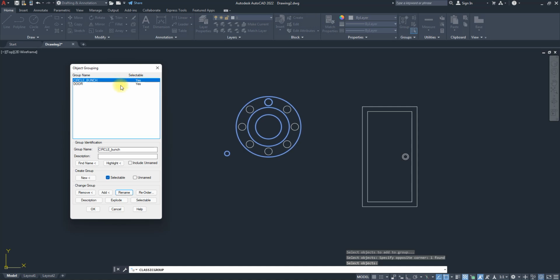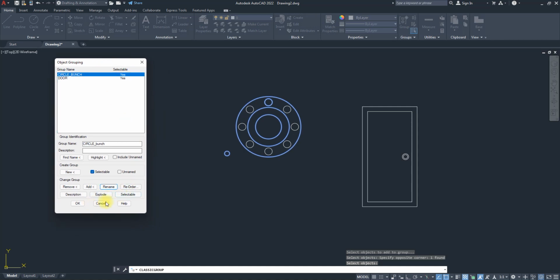So once you are done with everything, then if you now want to ungroup, you have the option to also ungroup. You can also ungroup this object. And you notice in this place there is no ungroup icon. Can you find any ungroup icon there? No. What you can see is explode. So if I say okay, explode, and notice we don't have any group anymore. Do you understand? So the ungroup in this manager is the explode.